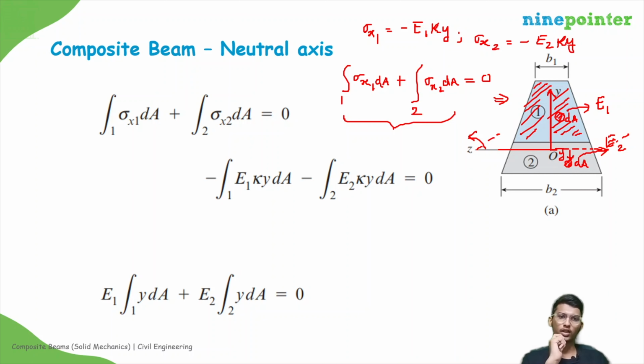One doubt is whether the radius of curvature for both materials will be the same or not. It will be the same, because if you take this duster and attach a duster of another material here, and try to rotate like this, the two materials rotate rigidly, with attachment. So the radius of curvature of both will be the same.